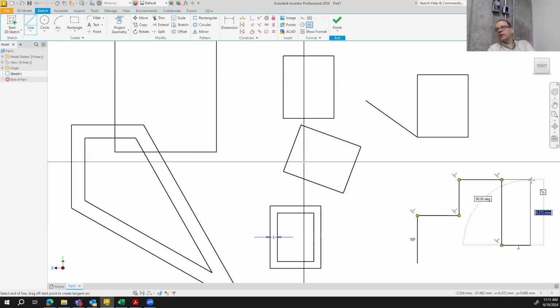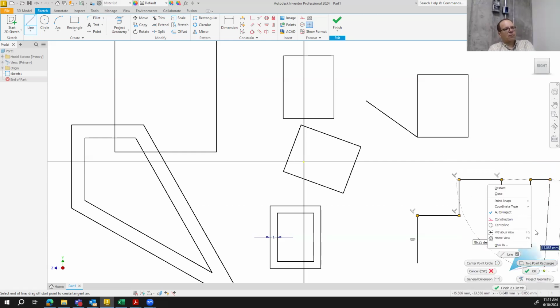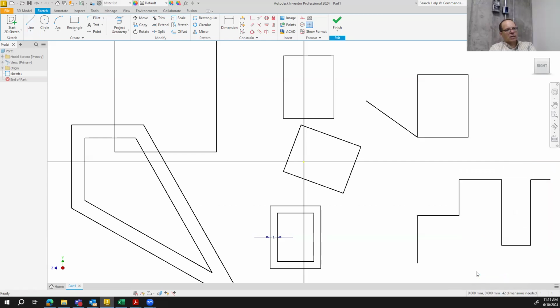You can see that connection. So it now thinks that you definitely want to have this at the same height. It makes a connection between these two points, so that if you start playing around with other lines, you won't be able to dimension it separately, because it really thinks that the vertical location of this line and that line are supposed to stay the same.